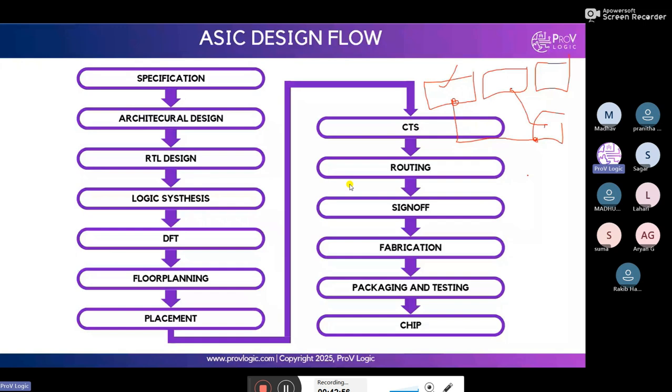At the same point in time we will check the static timing analysis, how the setup time and hold time are working, whether there are any clocking issues or metastability, and whether it is able to control the clock gating. Everything will be checked in clock tree synthesis. Ma'am, the power gating concepts will also be here in CTS only. Okay, ma'am.